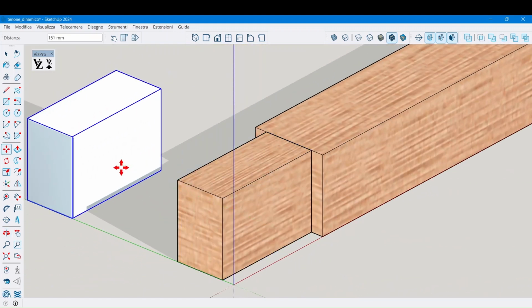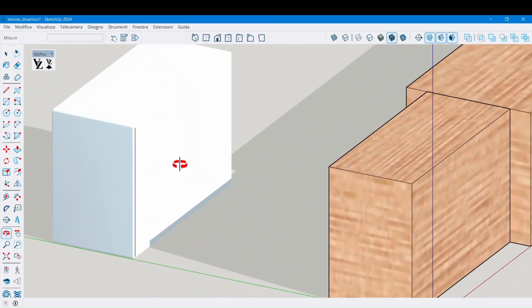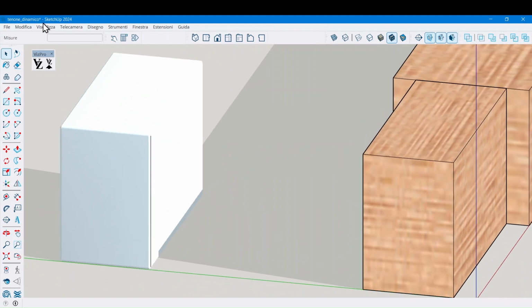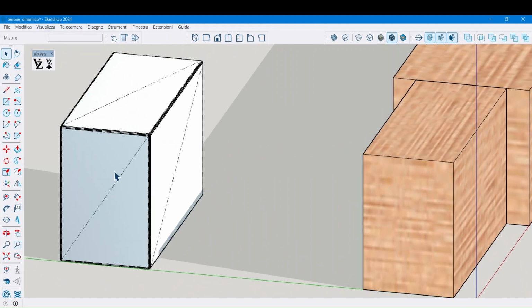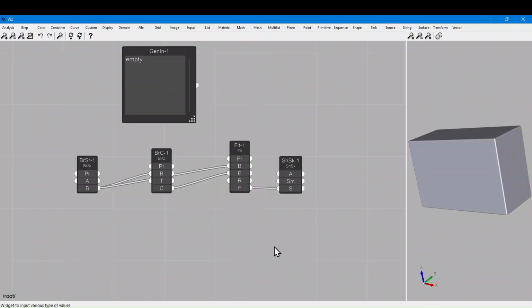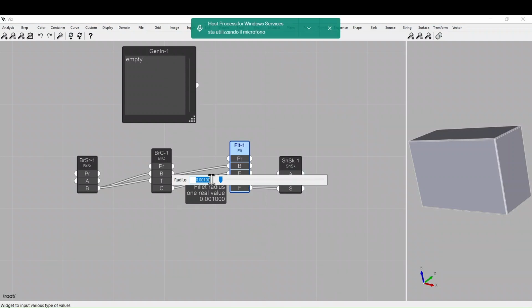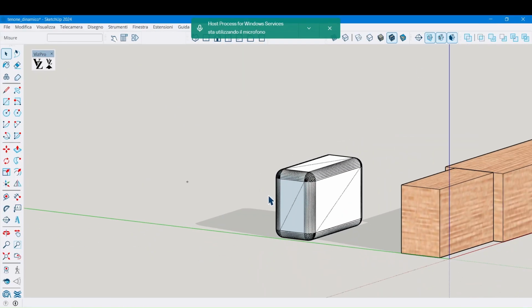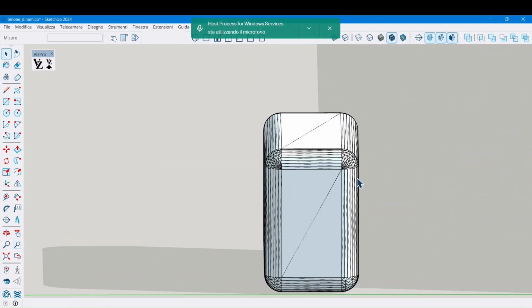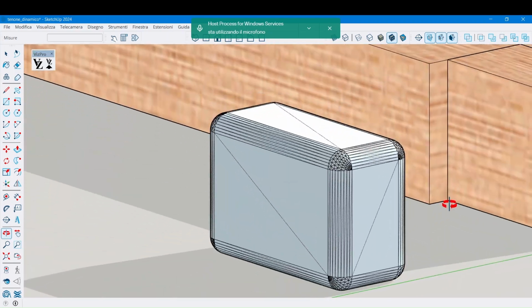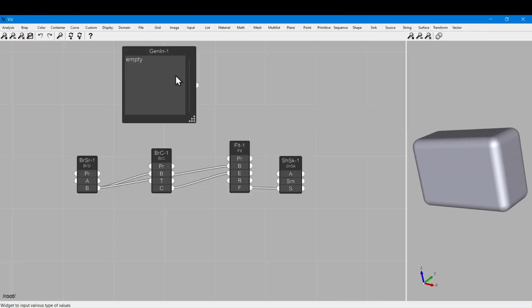It seems to look not very good. For seeing all the geometry, go to Visualize, Hidden Geometry. Let's make a change on the fly. I'll input 8 millimeters radius. I'll get back to Viz.